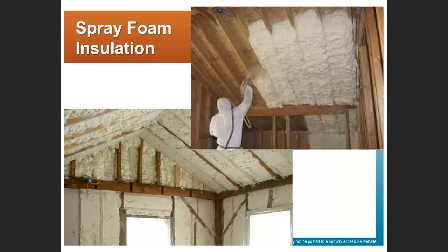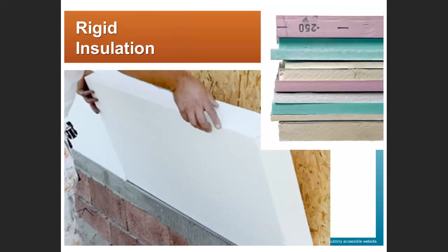Here's spray foam insulation. Again, this is going to be more expensive, but you will achieve better thermal performance, higher R value, and it certainly works better if those stud spaces are irregularly shaped and don't necessarily lend themselves to fiberglass bats.